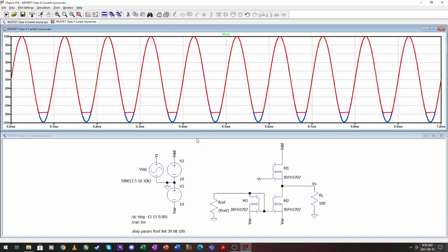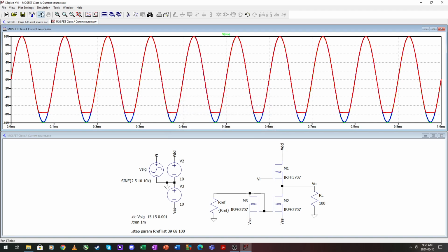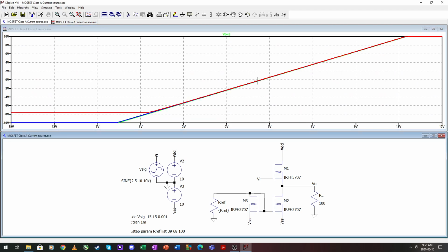Any case, let's have a look at the DC characteristic. And here again you can see that big offset due to the fact that you're using a MOS, but it can be fixed. So not much to show here. The only decent thing to show is this almost rail to rail operation, and the fact that we have a huge offset on the input and output.